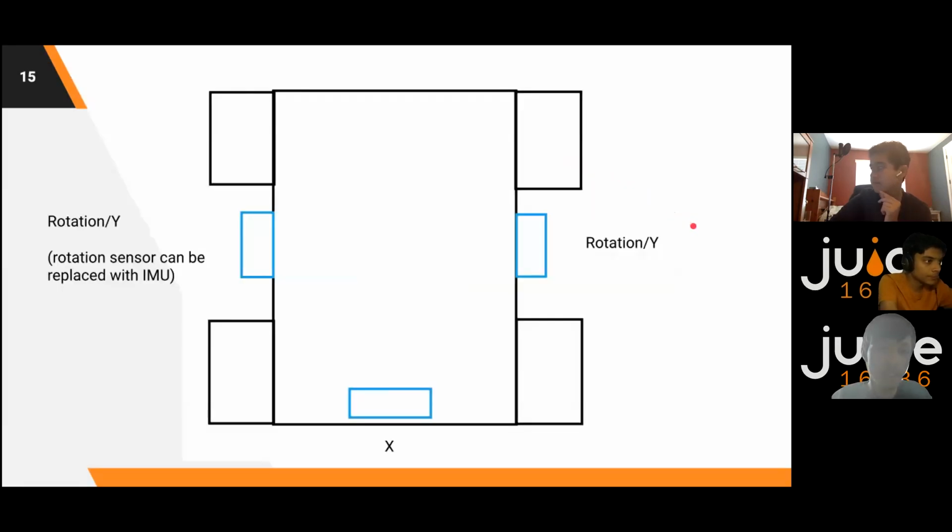And this is a basic setup of how you would orient your odometry modules. Technically you could have them in any orientation, but that's just extra work in order to calculate the different changes in position. For the X tracking module, you would have it perpendicular to the robot's forward motion. Say you were strafing, then the omni wheel would also be facing in the strafing direction, so that you can accurately track the strafing movement.